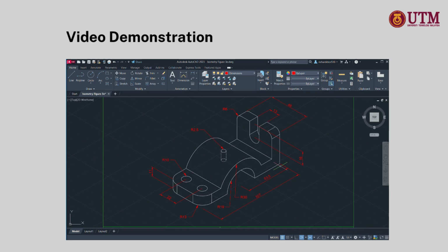Moving on to dimensioning standards. Dimension means giving the necessary size information on a drawing. Drawings should follow recognized standards such as ISO or ASME. These standards help make drawings clear, consistent, and acceptable in engineering practice. The main dimensions that should be included are the length, width, height, diameter, or radius. These dimensions are essential because they define the actual geometry of the object, and without them, the drawing becomes incomplete and useless for fabrication.